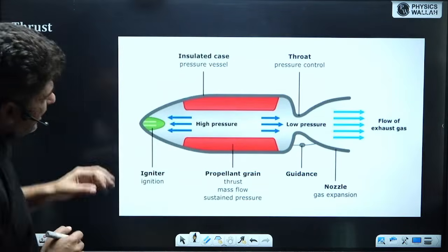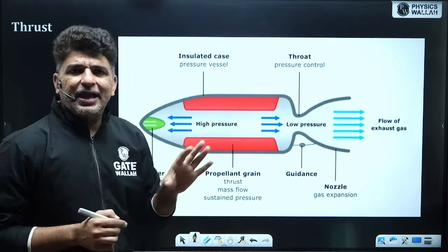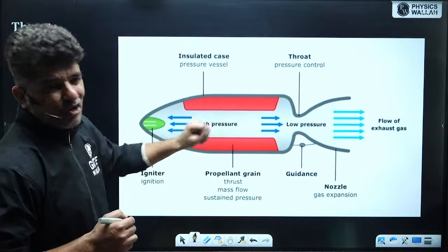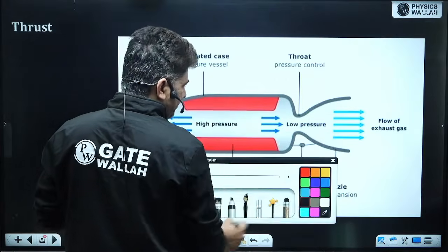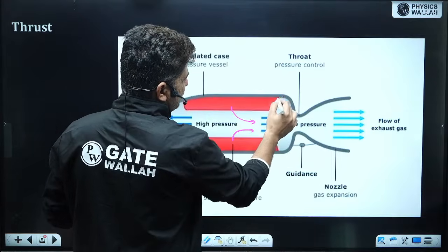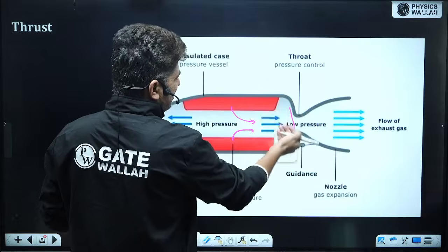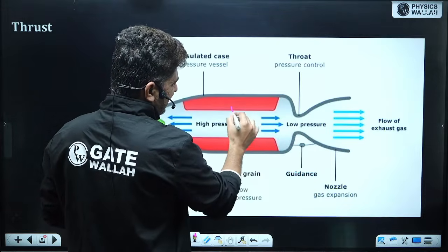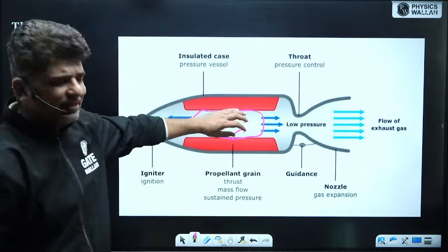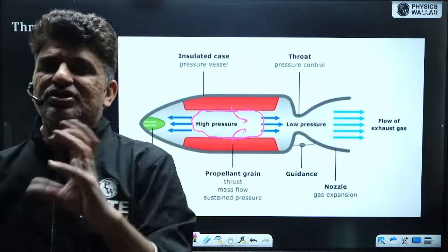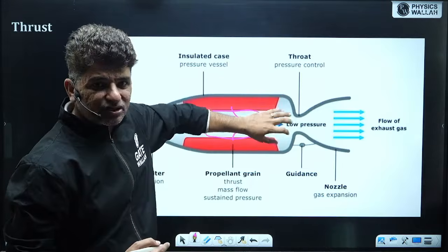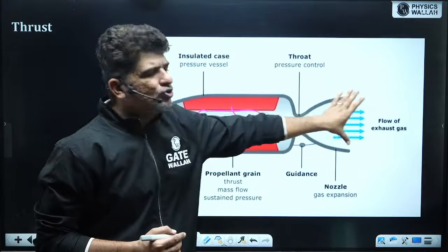So how do they develop thrust? They have an oxidizer and a propellant, the fuel. Let's say this is the oxidizer and this is the fuel. They combine the oxidizer and fuel in a combustion chamber. This is generally not a regular combustion chamber; it is a slightly different variant. The burning happens over here, in the region where the oxidizer and fuel mix and generate very high pressures. This high pressure propagates over here, passing through the nozzle and going out.